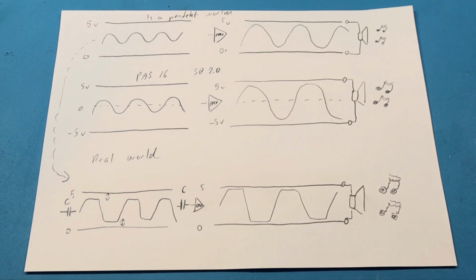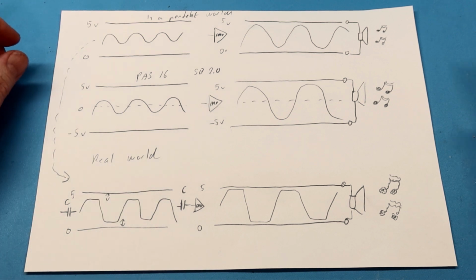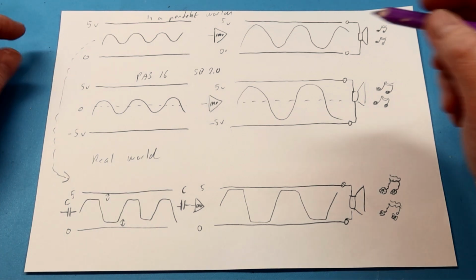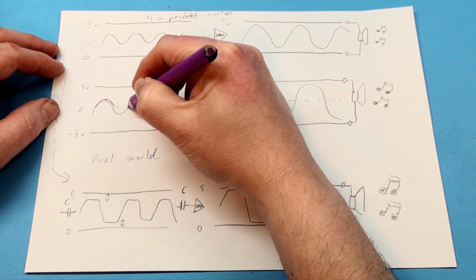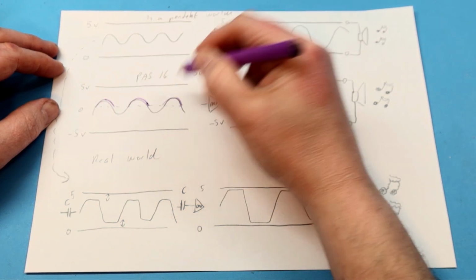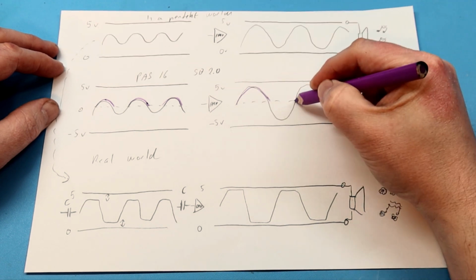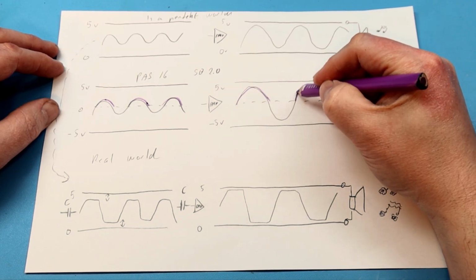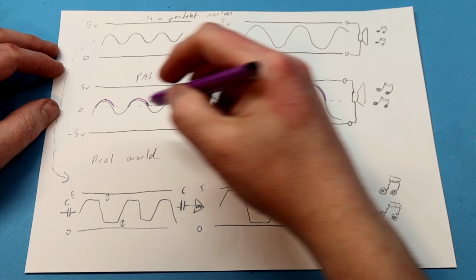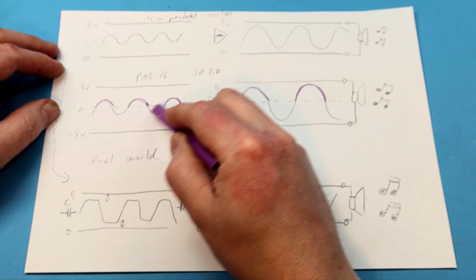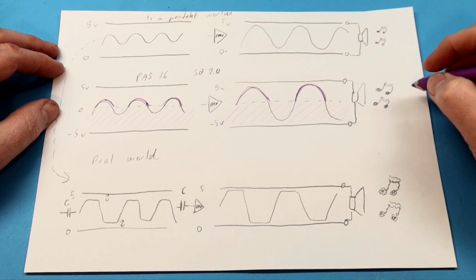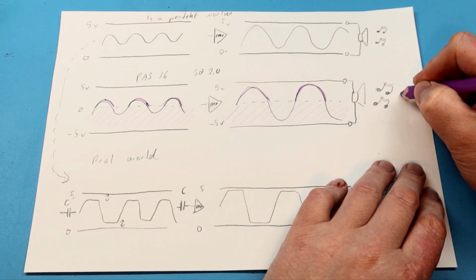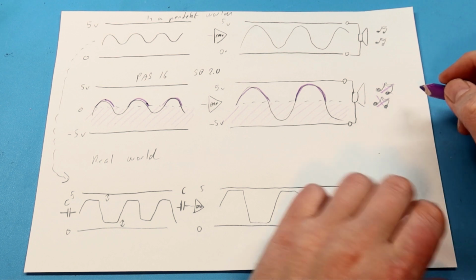But what happens if you connect your Sound Blaster 2.0 or your Pro Audio Spectrum to a computer that does not have the -5 rail present? The card will as such work, and the ISA bus and everything logical on the board will work without the -5 volt rail. But as we saw in the start, the audio circuits depend heavily on the -5 volt.